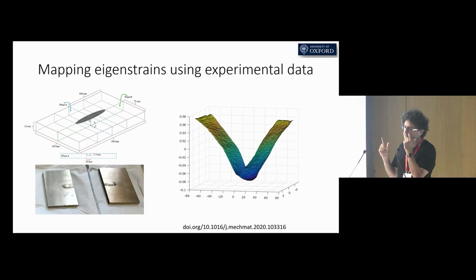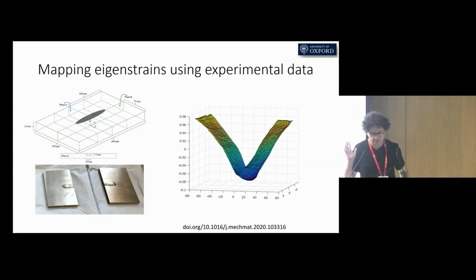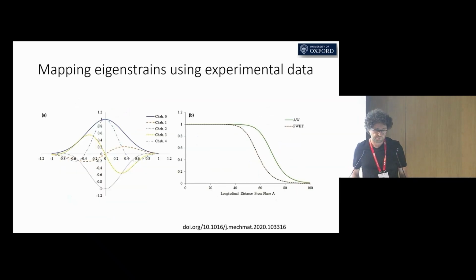But I want to mention that this information belongs to out of plane displacements, and similarly, the stresses relaxed are assumed to be only out of plane stresses. And this data is used for the determination of the distribution of eigenstrains within this symmetric domain.